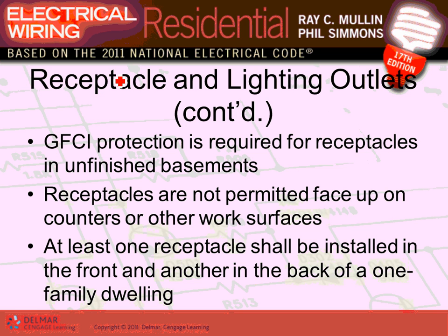The GFCI receptacle, guys. Remember the kitchen countertop receptacles? How about outdoor? Matthew, if you have to guess, any location that has water. Outdoor receptacles. How about the bathroom? One receptacle in the bathroom, GFCI. How about countertop for the kitchen, GFCI? How about unfinished basement? Could that be wet or damp? Yeah, GFCI. So if you guys have to guess where GFCI are needed, always think, where is the location in a dwelling or a non-dwelling that there will be water or damp location?